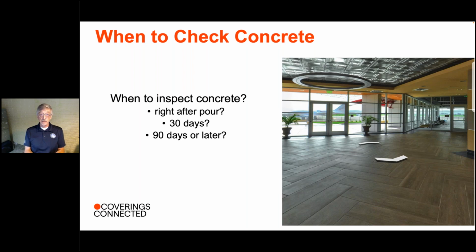It might have cured some more, and in the curing process, it might have curled, causing the concrete to become less flat over time. And in this particular job, the tile contractor did come in at the 6-month point, after the walls were built on top of that concrete pour, after all of that glass was installed, and the tile contractor came in.